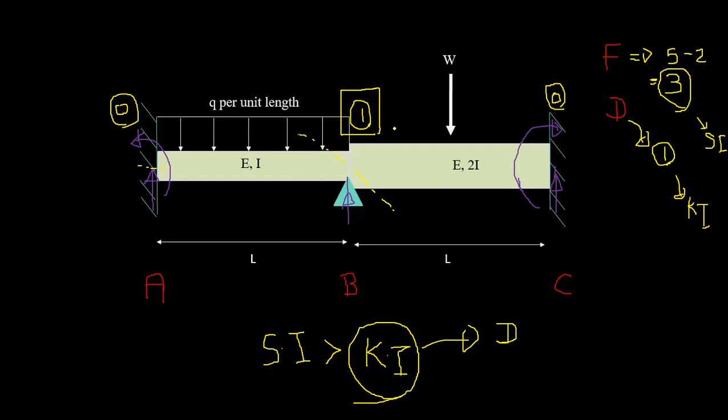So the easiest way is, right, one more thing, if you want, you can use force method as well, but when using force method, please consider, it will be easier for you to use hinge forming. The other method is not going to be easy because this is geometrically not consistent, right? This is EI and this is 2EI. So when you use hinge method, you automatically divide it into two parts and then you can solve it easily because you are considering each span separately. But if you are solving without hinges, it will not be easy, right? So we are working on this as displacement method, so we are fine, right?